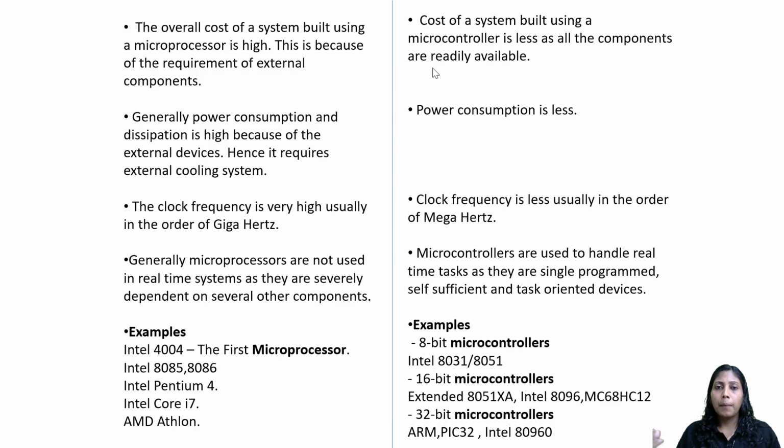But on the other hand, with microcontrollers there will be some limitation, because somebody is completely new to embedded systems. If you are starting, I will advise everybody to start with an 8-bit controller, the basic controller, understanding all the stuff properly. Then you can go for a 32-bit controller. That's how you'll be able to compare and learn the difference, and how each is programmed. For example, how you can enable a timer or PWM, or how you can connect an LCD and program that. Then you can come to the 32-bit controller.